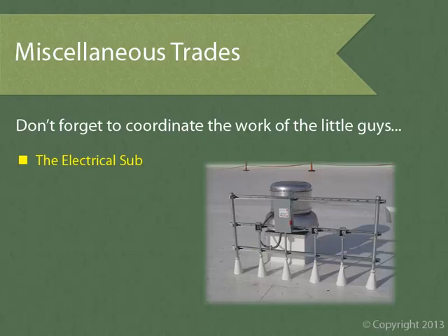Let's talk about roof jacks for a moment. First, they typically need to be spaced 12 inches apart. The dimensions for this spacing may vary among manufacturers and roofing types, but a minimum 12-inch separation is pretty standard. This is so the horizontal flange of the roof jack gets a proper, clear, and flat transition with the roofing membrane. Of course, this 12-inch separation isn't just required between conduit or pipe penetrations.